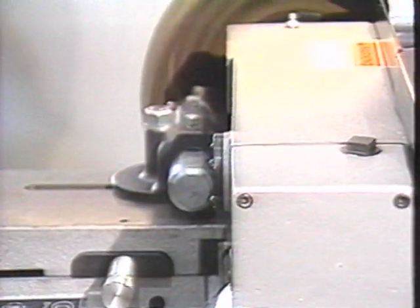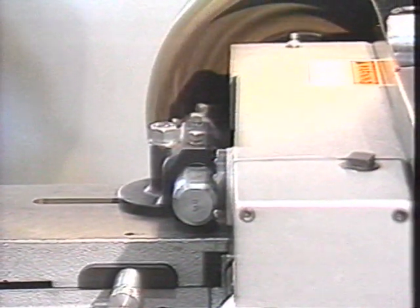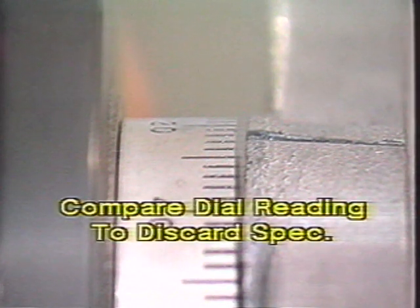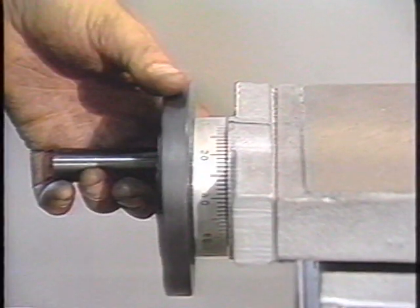Crank the cross-slide wheel until the cutter tip begins to cut the drum face, and continue cutting into the drum face until a light cut line is visible around the entire diameter of the drum face. Read the cross-slide micrometer. Compare this second number to your discard specification. If the deepest groove exceeds your discard specification, you can tell your customer that the drum is bad before you cut the drum beyond discard. You've given every consideration to the condition and size of the drum.